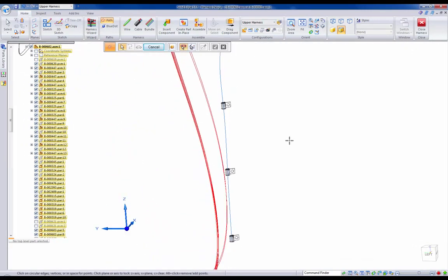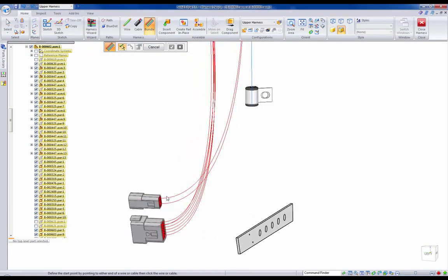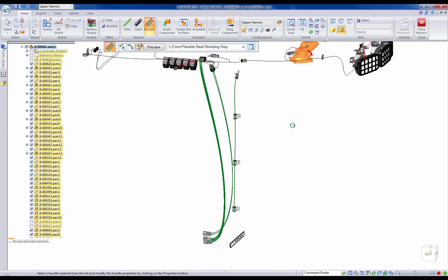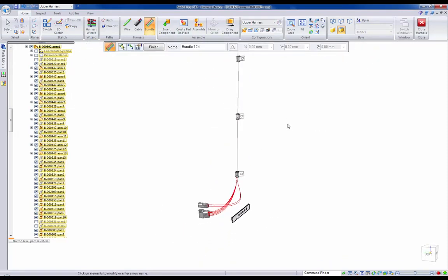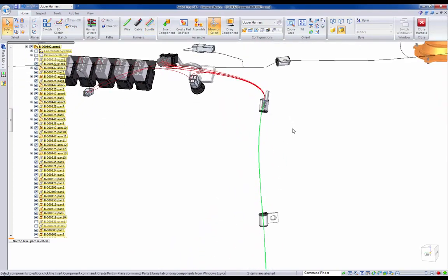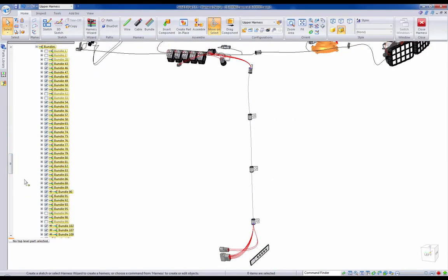Keep in mind at this point that users can choose to define cables inside of the E3 software, or they can quickly create the desired results directly inside of Solid Edge using our bundling options. Once all of our wires are selected and we've chosen the path in which to run them, Solid Edge allows users to define sizes and colors of the bundle to be represented as the final result. Once in place, Solid Edge can represent the realistic size of the wires and cabling to allow users to ensure their harness is represented properly in the model.